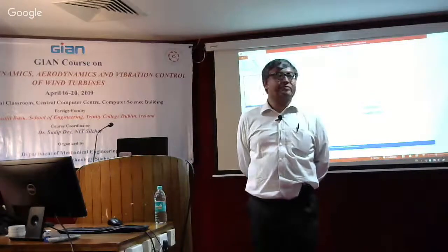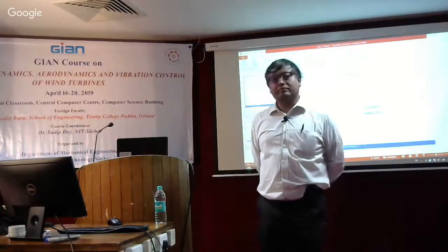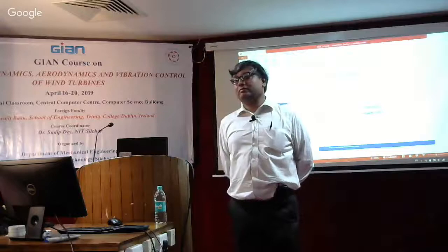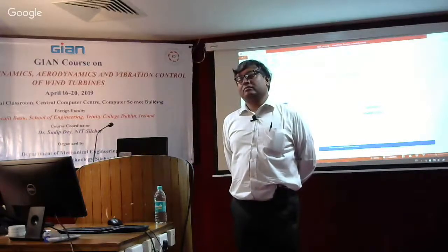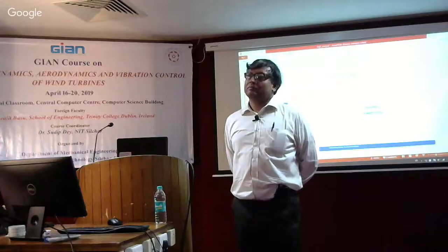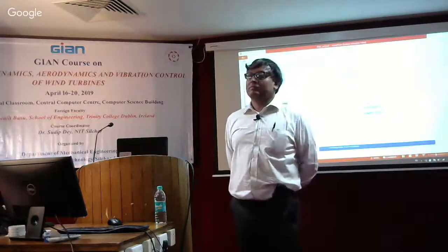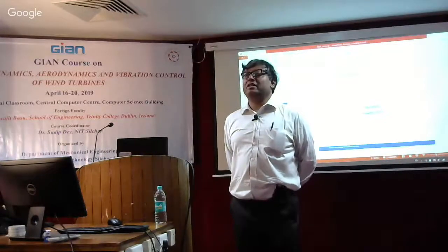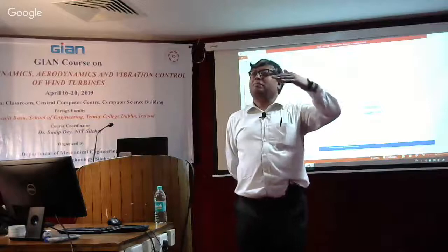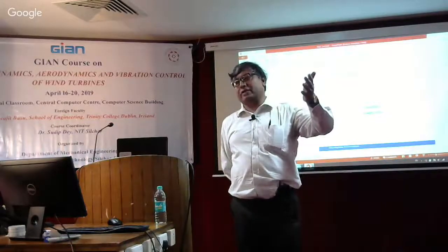So I have a question related to the same, the mean wind velocity profile. You're talking about the log, there is a log of Z by Z0. So the reference Z0, what should it be? Is it like the previous year? No, the reference is any other particular point for which you have the velocity known.